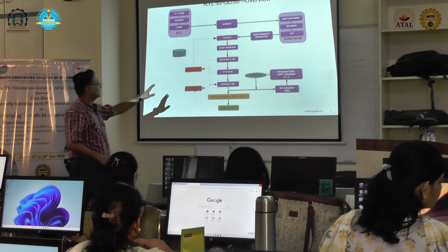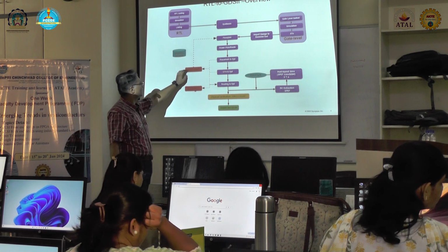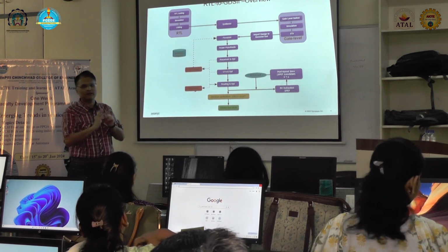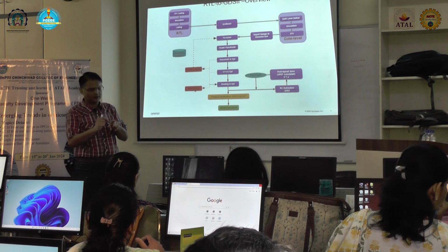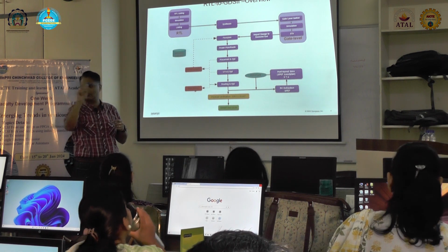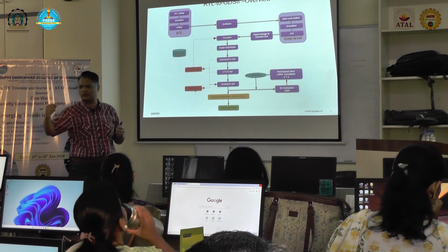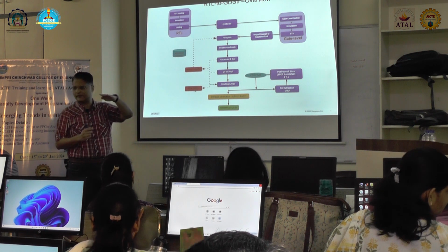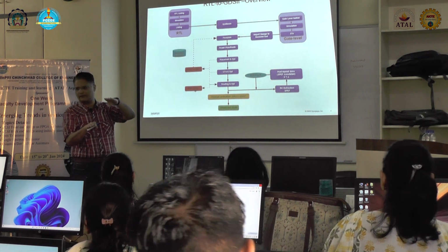So whether and when power integrity is being performed, along with that the crosstalk is also being performed. So crosstalk is like if two signals are running parallel, what might happen is that if one signal is, let us say, continuously 1 and the other signal is 0, 1, 0, 1, 0, 1, 0, 1, the signal which was continuously set starts to interfere with the 0, 1, 0, 1, 0, 1.